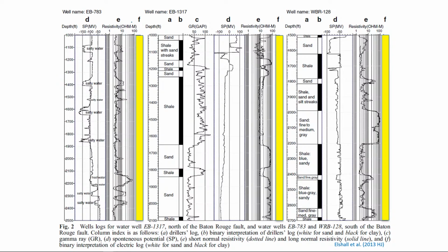Now this is resistivity, the electrical borehole resistivity, and you see all these kicks here. This is clay, low resistivity. This is sand, high resistivity. Then you go here, clay. This is sand, high resistivity. Then clay. Then you get sand here, and sand here, and sand here, clay, and then sand here, and then clay.